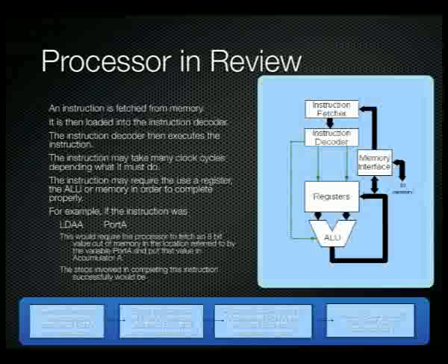Give the memory interface the address of port A from the instruction. So the address of port A is actually with the instruction, and it gives that to the memory interface section. Echo the address of port A onto the address bus. So that simply comes out of that I/O device onto the address bus. It simply sets the read line high. It reads the value from the address of port A via the data bus into the temporary register. And then it simply moves the value read from port A, which would probably be in some memory address register or some memory data register, from the memory data register into accumulator A.